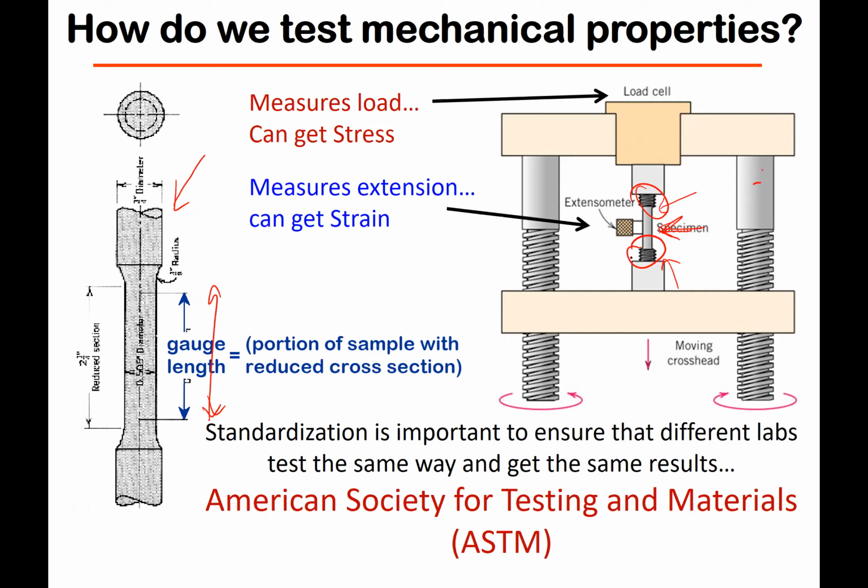And so with metals, this can be done with great accuracy. With ceramics, what tends to happen is as you're even putting in the screw, your material can fracture quite easily. And if you don't design the screw correctly, it won't break down the line, right? What you really want is to be able to pull the specimen and have it break right in the middle. And so what will happen is your ceramic material will actually break where the screws are, where the material is actually attached to the load itself, thus rendering this measurement pretty useless, and thus also not a good use of your time.